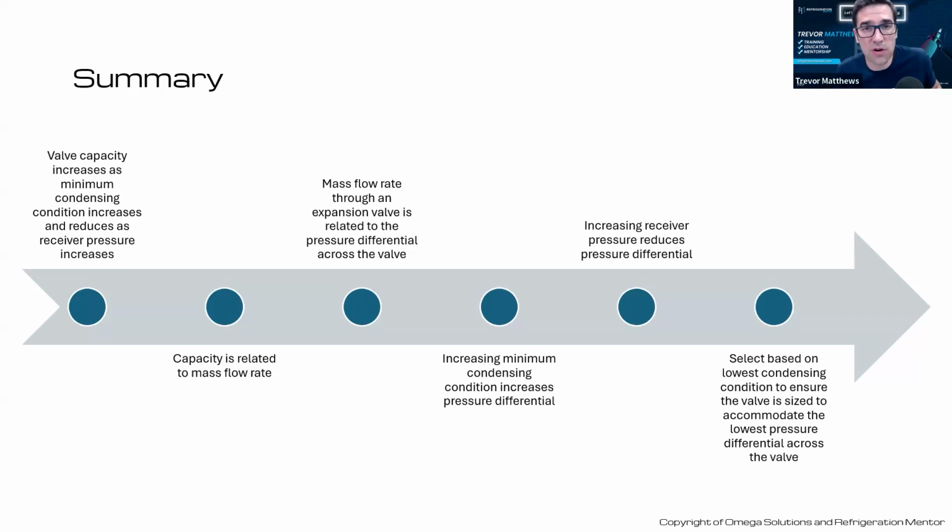Are you doing a small store where it's like 5 cases, or are you doing a large one where there's 100? Is it an industrial? Do you have to put them in parallel? How do I size when I put them into parallel and I need 4 or 5 of these high pressure valves? There's a lot of things that you need to understand when you're designing a CO2 system, whether it's big or small.